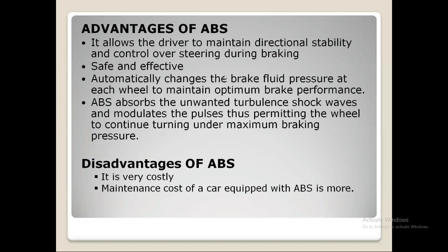It automatically changes the brake fluid pressure at each wheel to maintain optimum braking performance, and reduces the braking distance. ABS observes the unwanted shock waves and modulates the pulse, thus permitting the wheel to continue turning at maximum braking pressure.